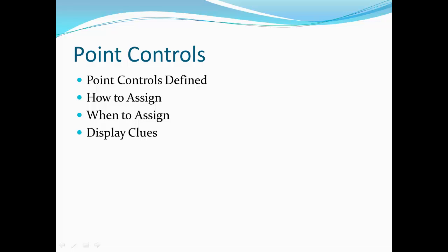Point controls. Point controls are the most powerful tool in Roadway Designer. They allow the manipulation of any point on a template regardless of any other constraint, definition, or rule. They are useful in assigning superelevation, controlling corridor connections at intersections and gores, following alternate geometry such as independent ditches and intersection radii, or manipulating null points to activate display rules.